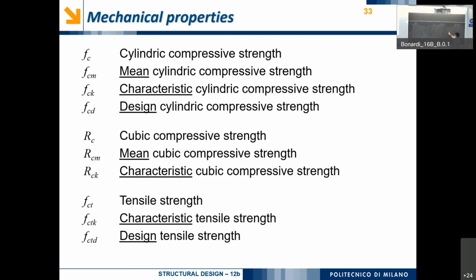If I have to do my safety computation for that building, maybe I don't want to use the mean average compression stress that is associated with the samples that I have used. Because I know that 1/2 of the samples, roughly, will be able to carry this level of stress, but 1/2 will not. Okay, so that's not a very smart thing to do.